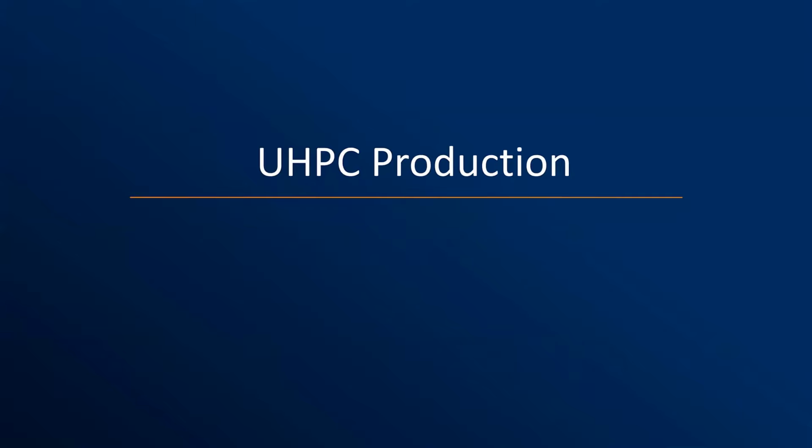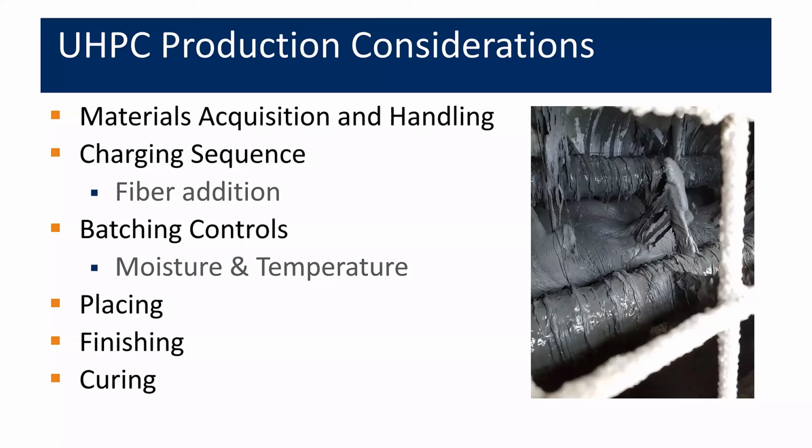All right, so I'm going to come back in now and talk a little bit about the production of UHPC. UHPC can be produced generally using similar equipment, same forms, for example, as conventional concrete, but there are some additional areas that need to be considered. Obviously, materials acquisition and handling may be a little bit different if we are talking about different raw materials than conventional concrete. The charging sequence of the mixer, especially handling the fibers, is something that's a little different. Batching controls, 2 important components for conventional concrete that are even more important for ultra high performance concrete, are moisture and temperature, and then placing, finishing, curing.